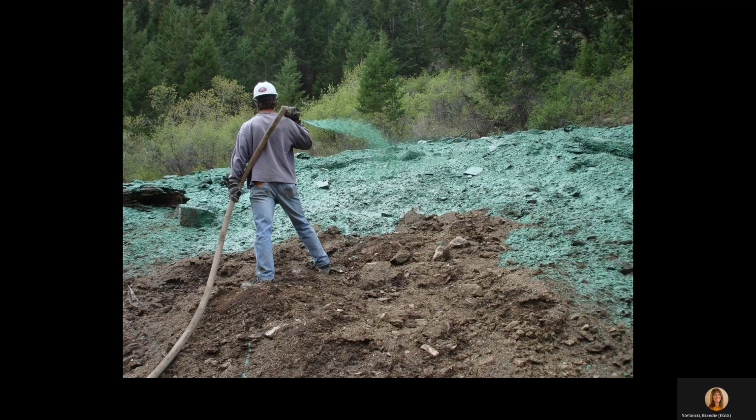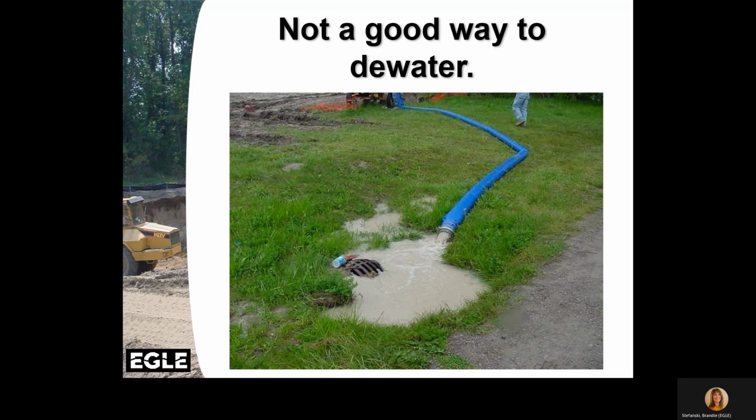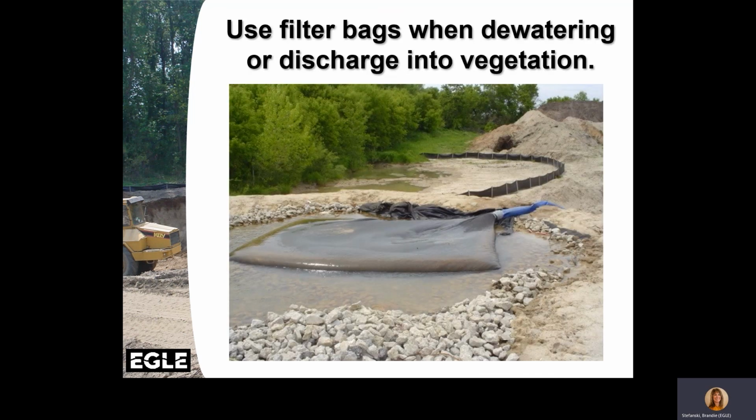This is a blend of mulch tackifier and sometimes fertilizer. It's rated the same as blanket and no anchoring is required. It is applied the same as hydroseeding. It may work better in areas not feasible for blankets or steep slopes. As we mentioned earlier, dewatering needs to be addressed with appropriate best management practices. Do not let sediment-laden water leave your site during dewatering activities.